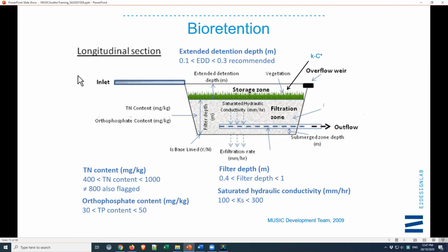That said, whenever we've looked at detention, extended detention in bioretention, what we've seen is that nearly always that drains out quickly. So if you have a bioretention sitting in a retarding basin or a detention system and you're modelling the extra depth of that system, you'll find that most of the time that will drain through the system really quickly anyway, and it won't necessarily be a problem. So it is a flag to say, be a bit careful, think about compaction and oversaturation and wetting, but at the same time, I wouldn't necessarily be worried if it's too high.